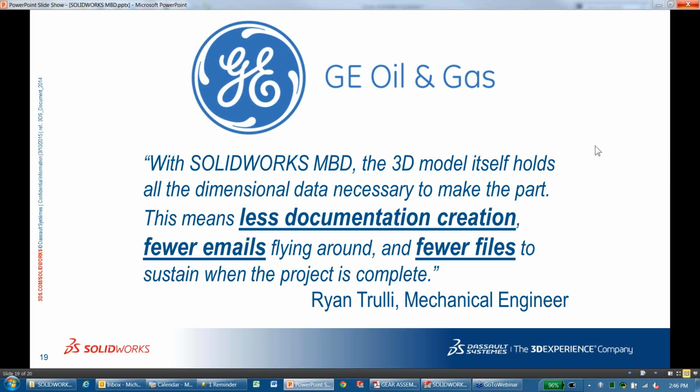But one thing it can do is that if you have, let's say, a STEP file or an IGES file that's coming from another CAD, you can actually do pretty much everything I've done today, even though it was not modeled inside SolidWorks, even though it's, in our lingo, a dumb solid. You can also dimension all of that inside SolidWorks as long as you get it into a part or an assembly file. Awesome.